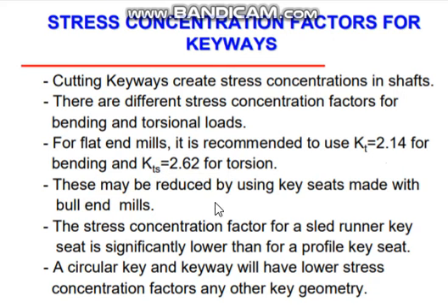These may be reduced by using key seats made with bull end mills. If you are using a bull end type of mill, the stress concentration will be reduced. The stress concentration factor for a sled runner key seat is significantly lower than the profile key seat. Anyway, don't worry about all these strange names.